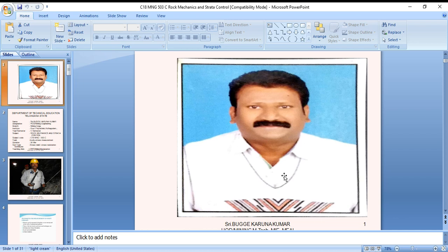triaxial, point load, protodiakonov, and slake durability characteristics. These are all laboratory tests, implementing a model to the underground. But sometimes you require in-situ stress measurements also. For in-situ stress measurements, you go directly underground and test by the stress relief and stress restoration technique.